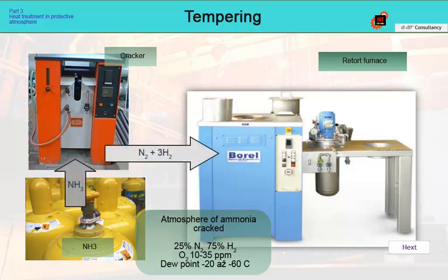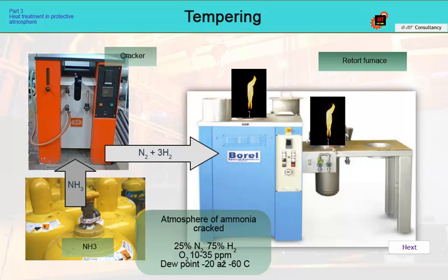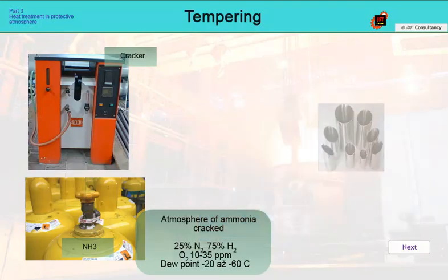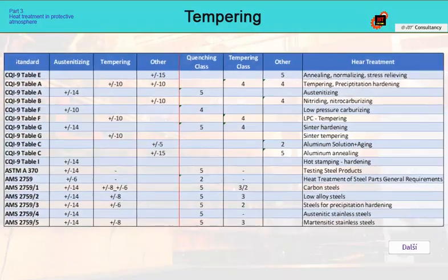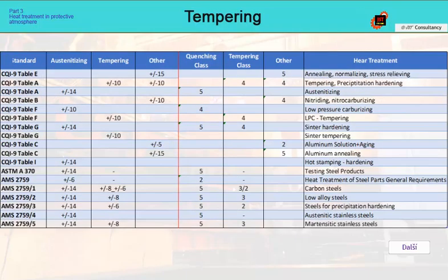Although it is explosive and highly flammable, when using retort furnaces with burnout at the outlet with retorts, there is no problem with either tightness or safety. This type of equipment and atmosphere has proven itself both for tempering small batches and for deoxidizing surfaces. The equipment usually works with two retorts, one in the furnace and the other on the cooling rack. Such tempering equipment is therefore very operational and efficient, and the results in terms of surface cleanliness are extremely good. In order to properly temper, all of the listed devices must meet some basic criteria.